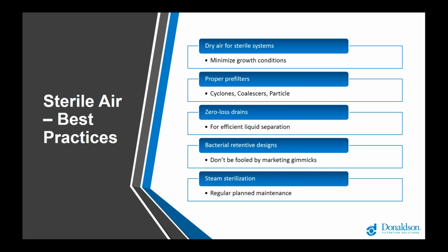And lastly, steam sterilized air filters. As they operate every day, they're sitting there collecting millions of bacteria, which can in and of itself form a hazard. If you're essentially making this concentration of bacteria, and if something happened that you didn't expect, a process upset, that filter could be compromised and ultimately send a higher than normal concentration downstream. So hitting that filter with high temperatures from steam will kill off any of the viable organisms and ensure that they're not capable of reproduction. Along with steam sterilization comes the proper maintenance planning and replacement of consumable parts like the elements inside. They can't operate effectively forever.